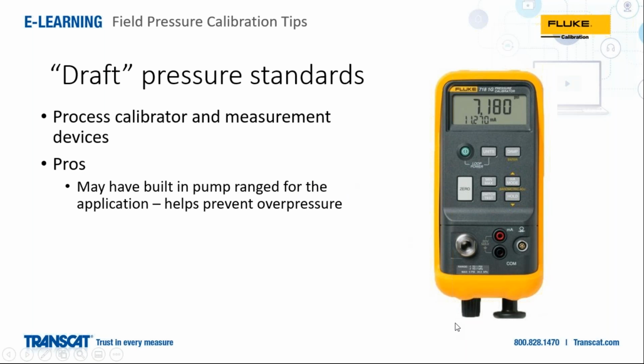You end up with this very, very nonlinear output from the raw sensor that you'd get without the linearization coefficients that we apply as part of the manufacturing process. So the answer is unfortunately no. You can't really swap ranges between the process calibrators that easily.